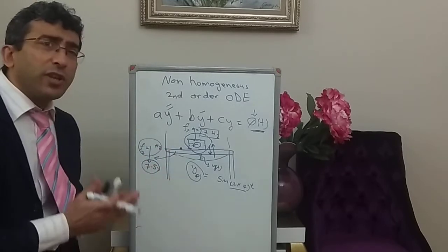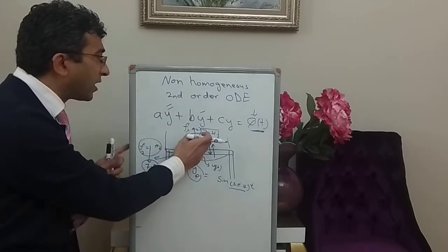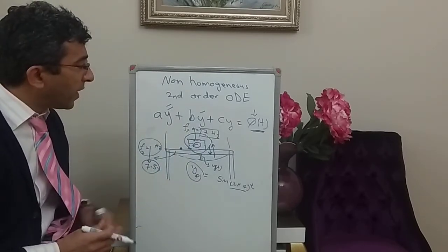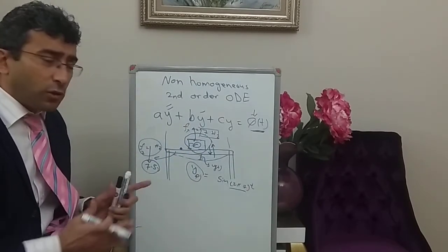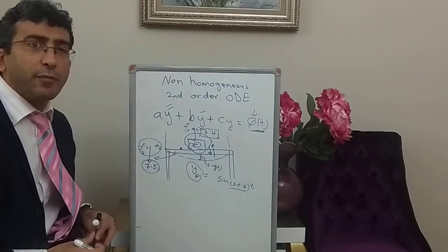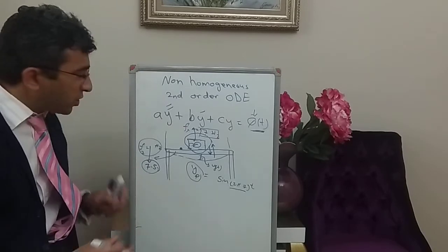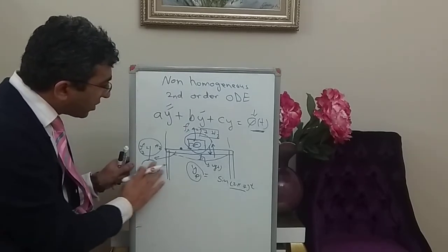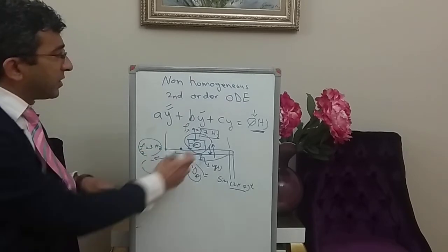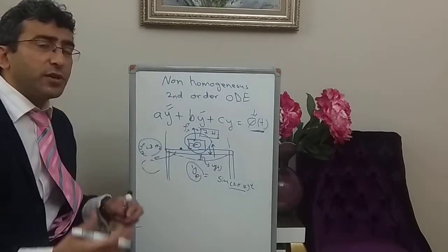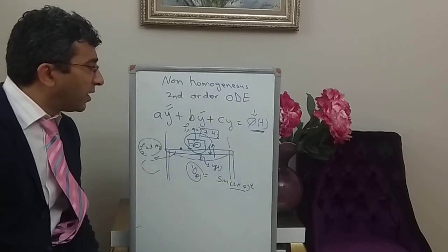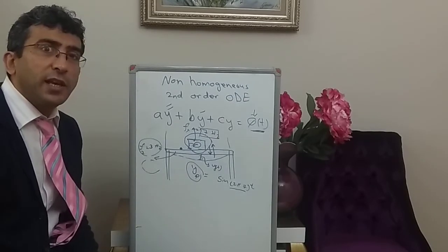If the exciting force frequency and the natural frequency of the slab are close to each other, you will have very high vibrations, and we call this resonance. So we should avoid such a thing. But 7 and 3 are away from each other, so the response is not that much, and there is not too much deflection if such a case happens.